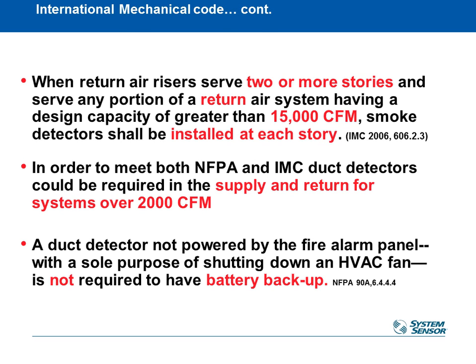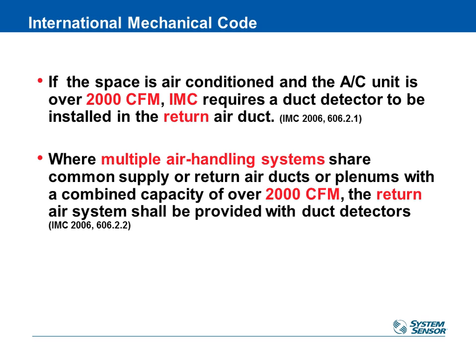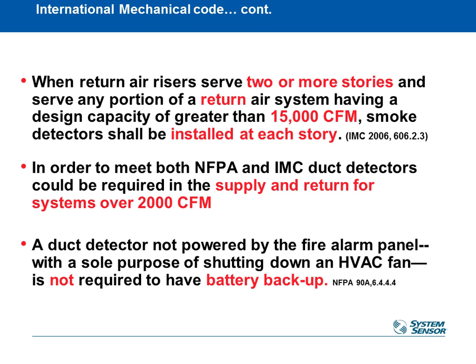Additionally, the IMC, like we said, has a requirement for putting a smoke detector in the return duct itself. But if you're doing it in a larger system, so if you have a multi-story building, 2, 3, 4, 5, 10 stories, whatever it's going to be, and that system is serving a portion of the return air system that has 15,000 CFM or more, then you need to install it on each floor that it's being supplied to, each story. That doesn't happen on a lot of projects. Obviously, it's a pretty unique job that you got 15,000 CFM, multiple stories. But if you do, you need to have a detector in the return duct for each floor of that return duct system.